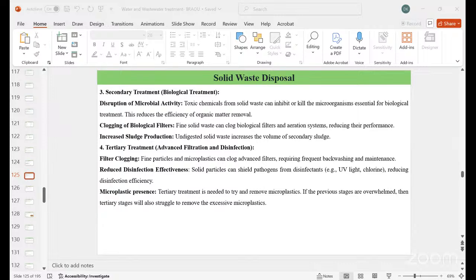The main advantages of this process are high thermal efficiency and uniform heat distribution, suitability for wet and low calorific sludge, low NOx emissions and better pollutant control. The disadvantages mainly include high initial capital and operational cost, and it requires pre-treatment, particularly for sludge.